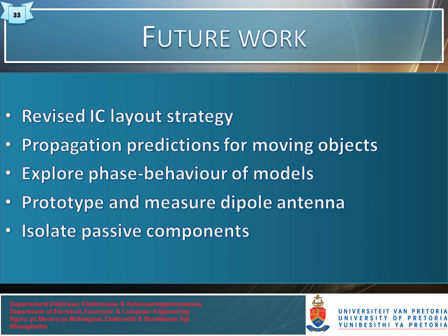Now, future work that emanates from the proposed research can be summarized as follows. Improvements on IC layout strategies are encouraged, and additional test structures to fully characterize all circuit components can be added to such circuit blocks. Thicker ground planes, next slide shows the picture of the current plane, enlarged and highlighted, would ensure less parasitic inductance and accurate results.